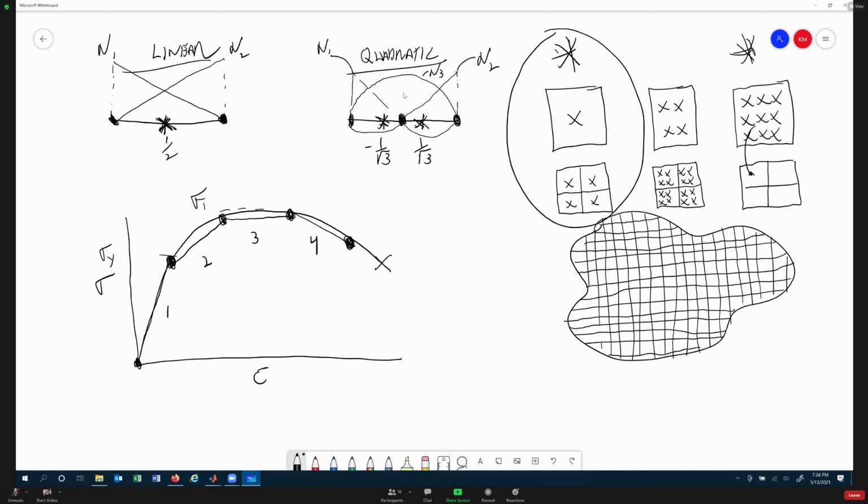Maybe you're missing a material parameter. Maybe you're doing something silly like you have a fixed boundary condition, and you have a beam or something, and maybe you've used SolidWorks and you have a joint or something, and this thing is swinging around. You're not going to get an FE solution based on that. It's called free body motion. It's not going to work because this would have to be kind of fixed.